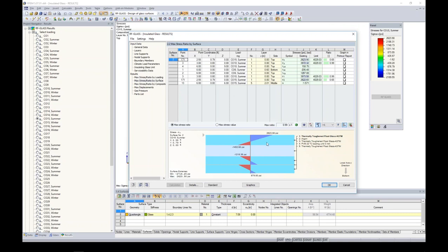And now we have our glass layer. Gas, we obviously won't have any stresses, and then we have our other 2 glass layers. So with this, we get the accurate shear coupling behavior based on the stiffnesses of our intermediate layers, which you can see here is modeled quite nicely with these diagrams that you can see for each layer.